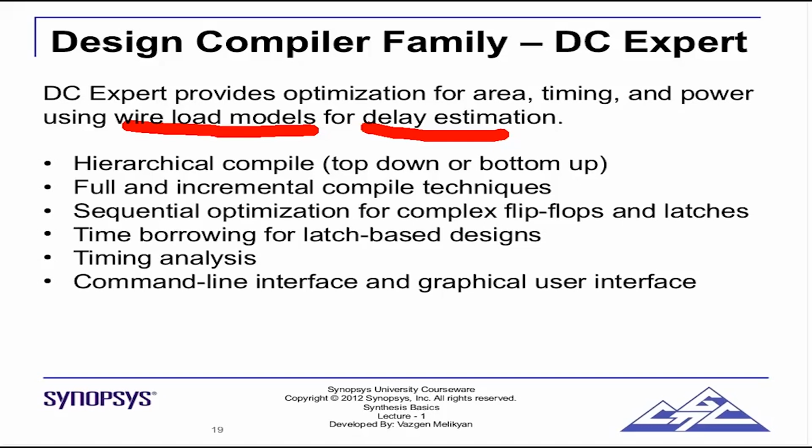It gives full and incremental compile techniques. It does sequential optimization for complex flip flops and latches. We saw time borrowing, so it is able to do that for latch based designs. Timing analysis: any synthesis tool should be able to do basic timing analysis to make sure the timing is met. We'll see a lot more of that. It has a command line interface and a graphical user interface.